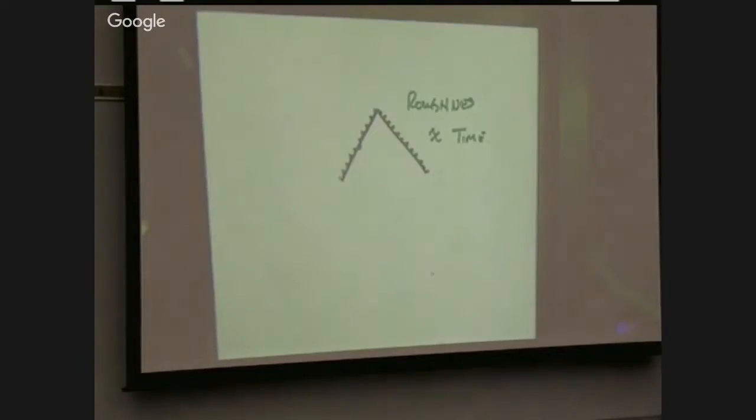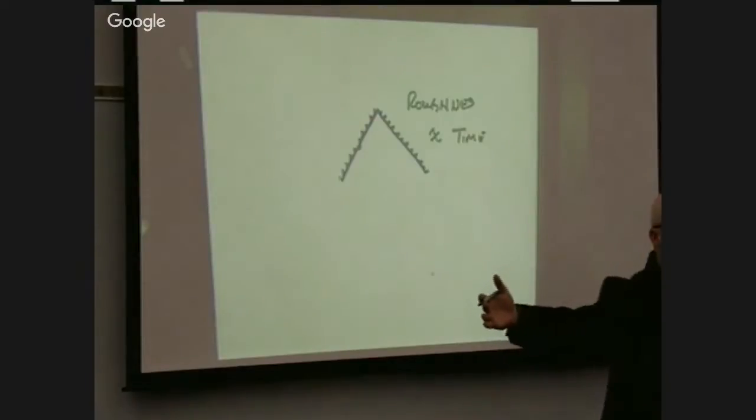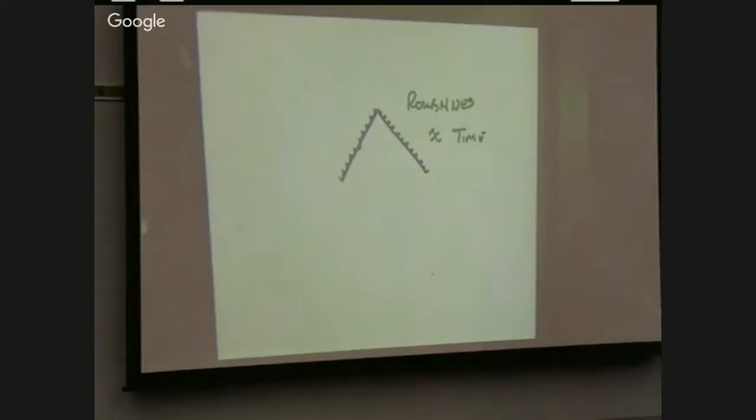Your time interacting with the machine tool was longer because, for one thing, you were learning how to interact with the machine tool. So setup was definitely longer on the 5-axis program. But the time that the tool was actively engaged removing material, was that longer or shorter? Much shorter on the 5-axis part. But you noted that you got a better surface with the 5-axis part. You got 3 different surfaces with the 5-axis part, because you did 3 different kinds of cutting operations on the 5-axis part, right?